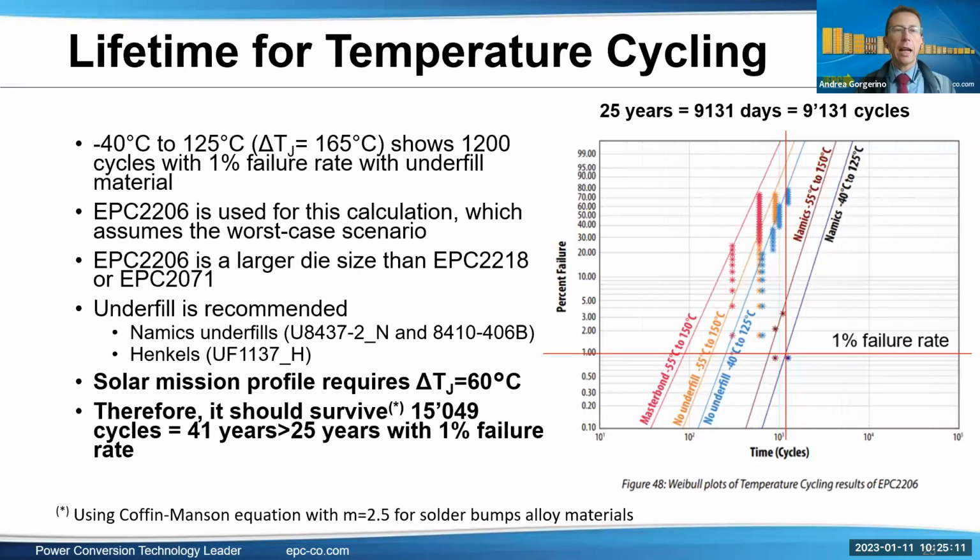So the last lifetime failure mechanism we want to look at is the temperature cycling. This is where it's more similar, I would say, to silicon devices. In the end, it's a thermomechanical type of failure. Our standard testing is doing temp cycling between -40 and 125 degrees C.